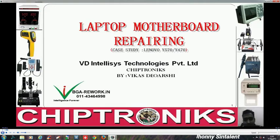In today's class, I will cover the V-in detection or DC bat out. I'll also discuss the difference between V-in and DC bat out, since in some schematics it's written DC bat out, whereas in some it's written V-in. Today in this class, I'll also cover the battery charging section: how the charger communicates with the IO controller and the battery, and also some theoretical aspects of ACPI. I will go into great detail on how to understand this entire charging section. So let's start with the class.